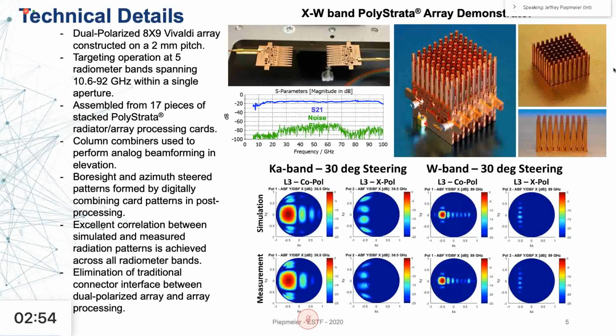The complete array is shown from several different perspectives on the right, and the array has beam combiners to form line elements in there. We verified the operation of this array using a near field antenna range to collect the individual line patterns, and then in data analysis did conventional planar array beam forming and beam steering to scan the beam using related software. And there was excellent agreement between simulation and measurement.